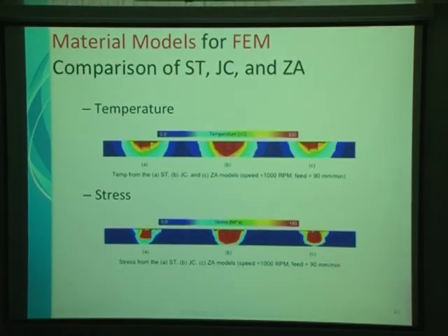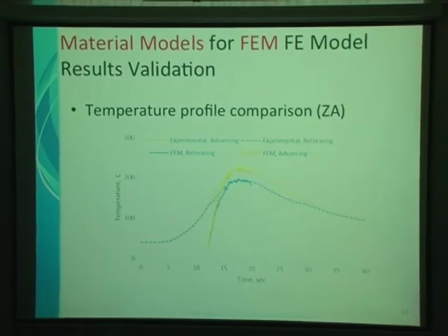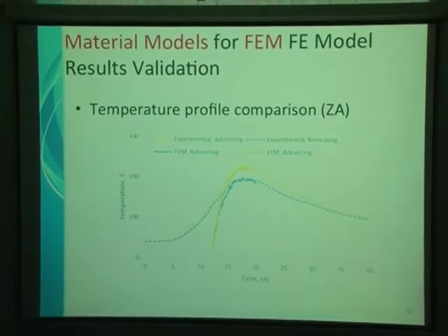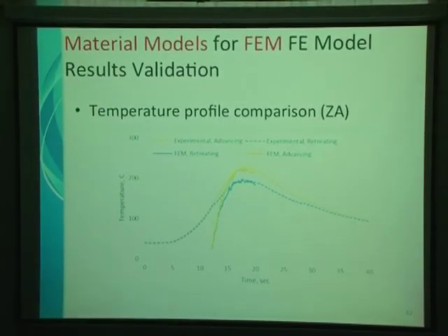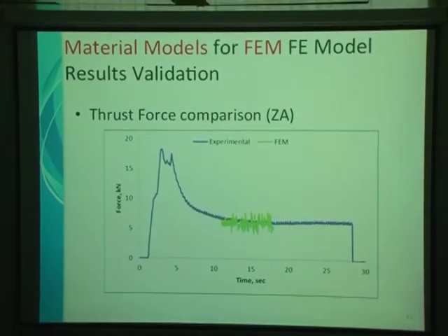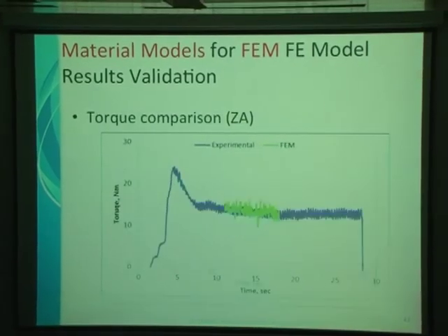Temperature and stress, you see the stress variation is quite a bit different for all these three models. But again, from this we were able to compare our FEM with the experiments. We have the Kistler running, and we also have the FEM, and the fits are excellent. Of course, it was not as easy as it looks, but again, this is your FEM simulations. This is the experiment for thrust, for torque.